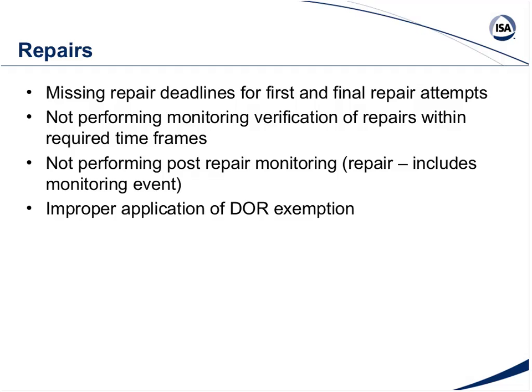Not performing enough post-repair monitoring, and again, some of them are dependent on the leak rate, so you want to make sure that we're out there. And then improper application of delay of repair. Can I really do a delay of repair on that component? Can I really do a delay of repair for a certain thing? That's particularly on pumps. You really want to look at those delay of repairs on pumps, because you see a lot of improper aspects of that delay of repair there.